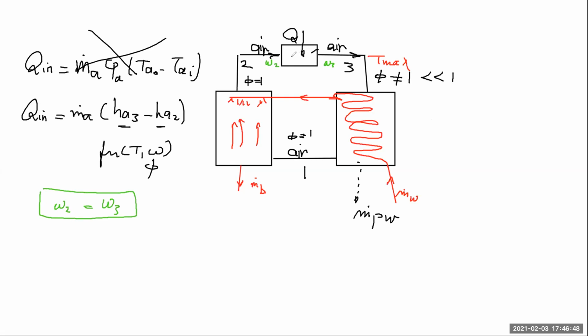There's no evaporation and no condensation, and that's why the water vapor content in the air remains the same. Temperature changes. Because of the increase of the temperature, the value of phi here is going to be less. But the value of omega, which is how many kilograms of vapor per kilogram of air, is going to remain constant. And this is the key for analyzing cases or solving problems that are dealing with the modified air heated cycle.